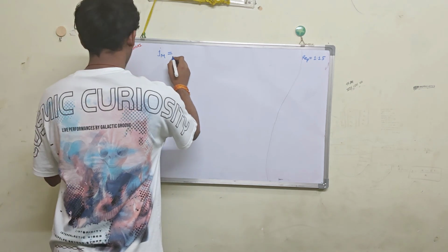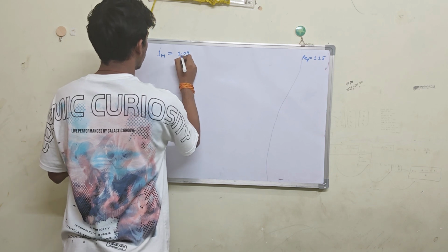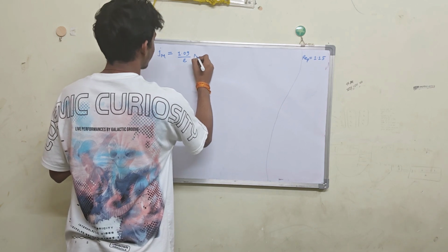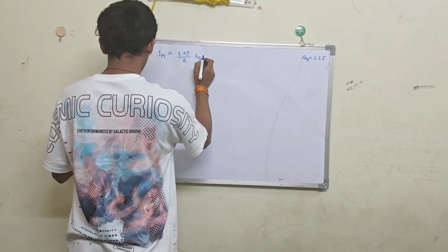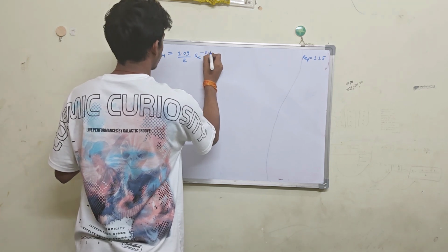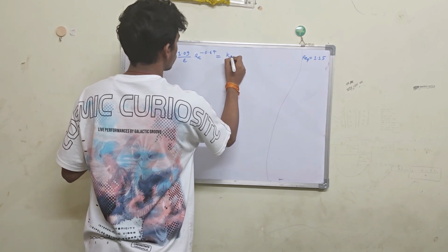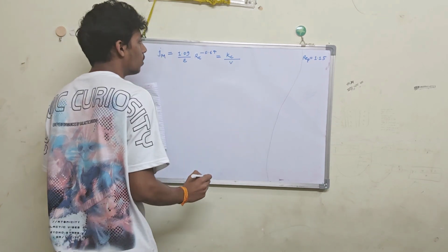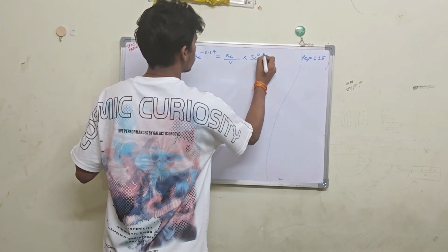Colburn factor for mass transfer is equal to 1.09 divided by void fraction, times Reynolds number to the power minus 0.67, is equal to mass transfer coefficient divided by velocity, volumetric flow rate, multiplied by Schmidt number to the power 0.67.